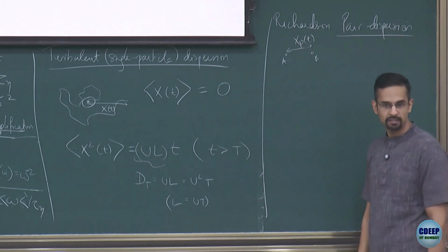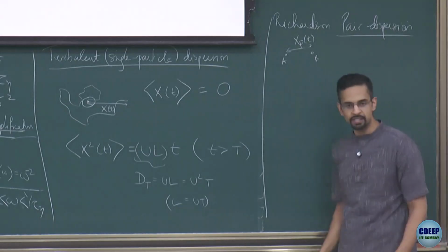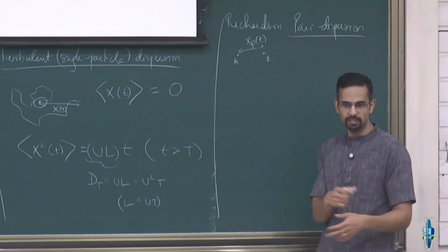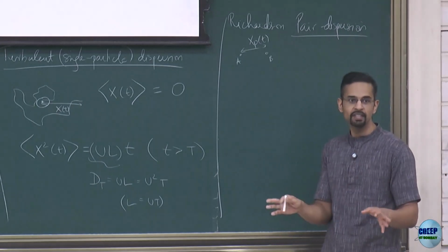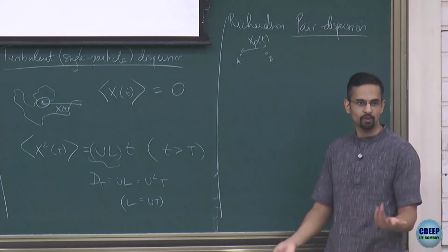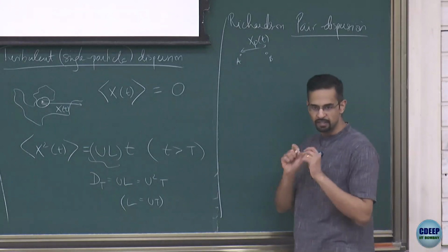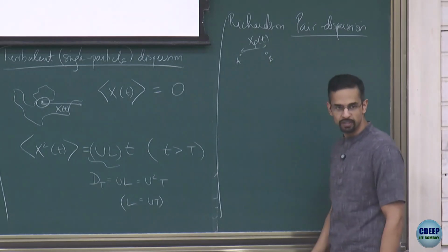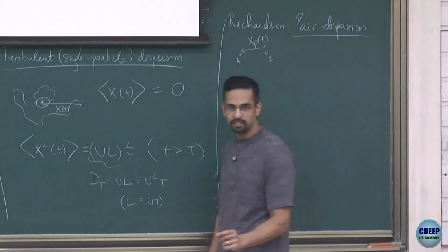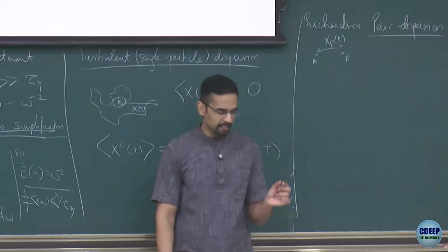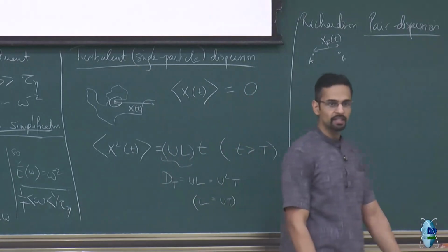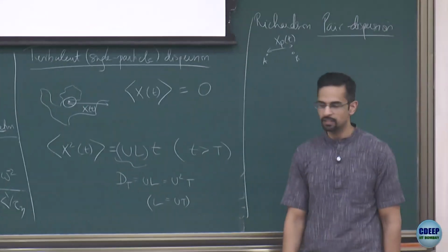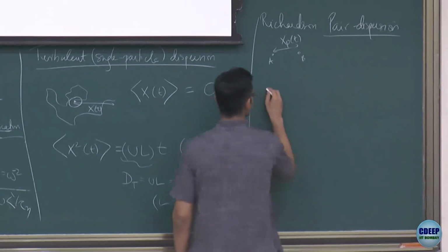Distance of the pair. Now again, because the flow is homogeneous, it doesn't matter where I release the two particles initially and what their relative orientation is. These things will not matter. If I'm doing an experiment, I would average out over these things across multiple pairs. But finally, I'll get a quantity for this xp of t, which will evolve depending on the starting separation. And the nice thing is I can take a very small separation below the Kolmogorov length, and I can watch how things change. So what should we expect now?